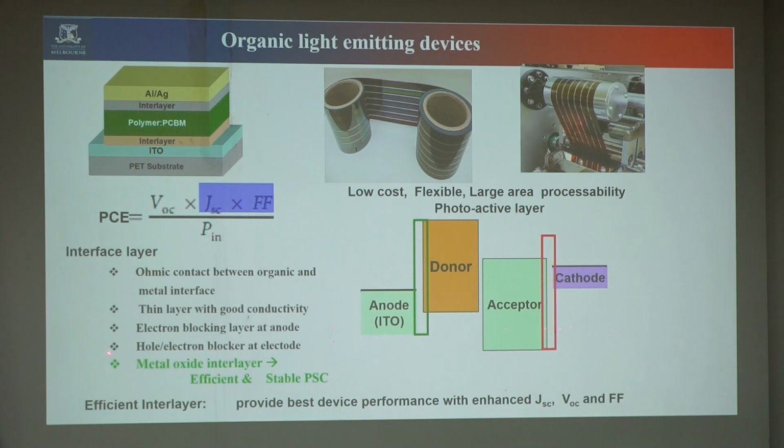In addition to a hole transport layer, we also have a blocking layer here, so that we extract only holes on this side. Sometimes when the exciton comes, a lot of charges go here and there. Electrons also come here, so the electrons should be blocked on this side. We have to extract only holes on the anode side.